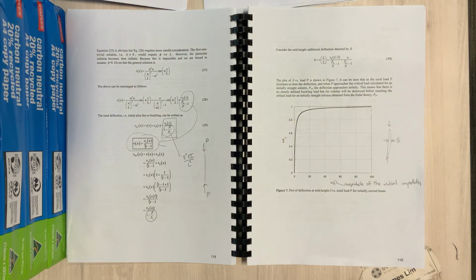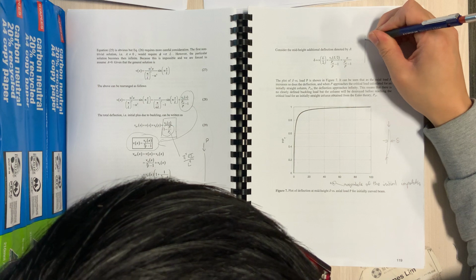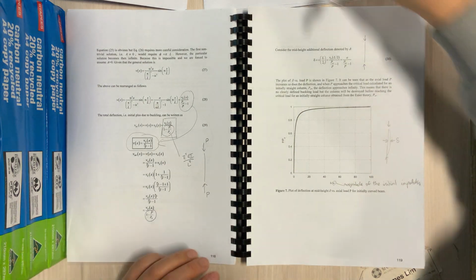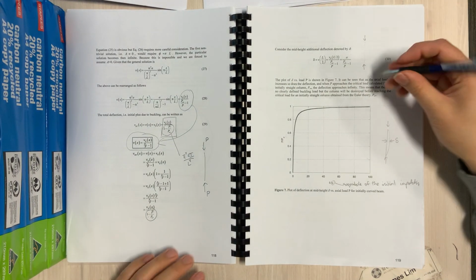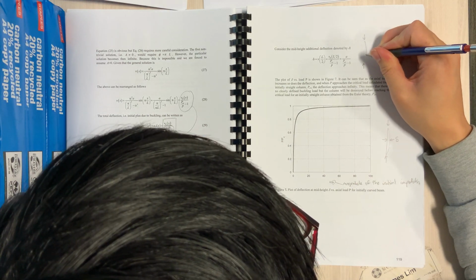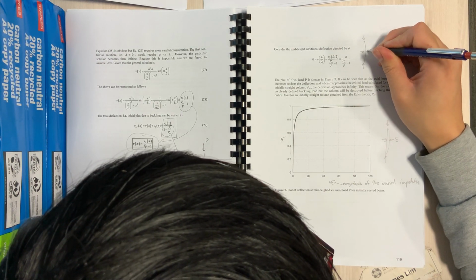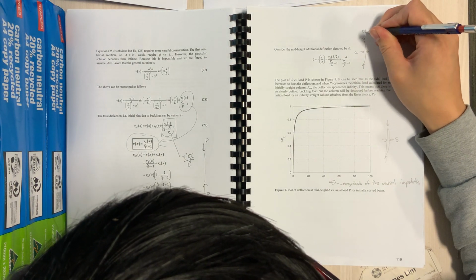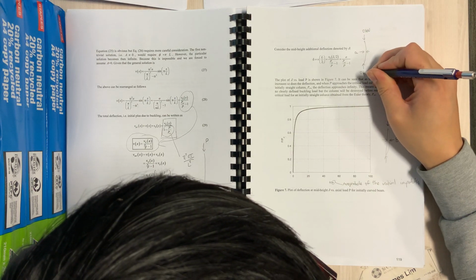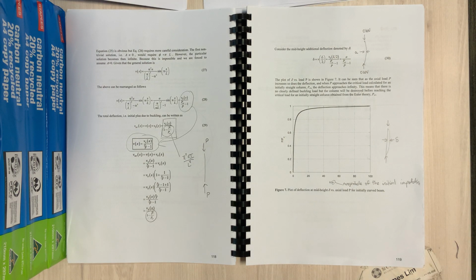So if we now go back to equation 30, which we see here, again talk about your pin-ended strut. If we said that the pin-ended strut wasn't perfectly straight, and it started off life with a deflection at the center, not a deflection, an initial imperfection A. So when you've got your load at 0 kilonewtons, your unloaded strut starts its life off with an initial imperfection of magnitude A.